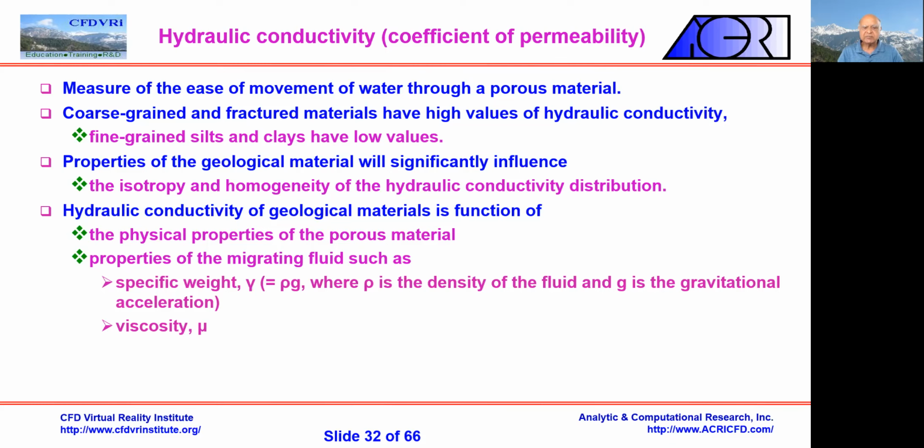It depends upon the specific weight, rho times g, which is the density of the water, and depends on the viscosity, okay. So the lower the viscosity, the higher the hydraulic conductivity. Of course, this is the viscosity of water we're talking of, water or air. So typically viscosities are fixed. So it basically comes down to how porous the material is and how easy it is to move, and that's called the conductivity. It will mainly depend upon the rock type and water properties we know.